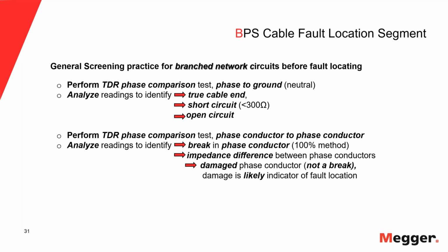We can also do a phase to phase comparison, like I was explaining on the industrial circuits. But overall, you have to keep your expectation low on using a TDR in these branch network systems. So it pretty much defaults back to the insulation resistance test.